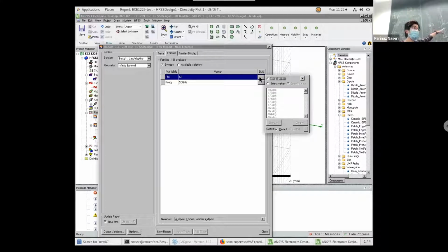Phi equal to 90 is Y, Z plane, right? Because we define phi from X to here. So either I can look at it in this plane or in this plane. Does it make a difference in the radiation pattern? No, right? Because the dipole is symmetric and the pattern looks like a donut around it. But let's see if that's true.